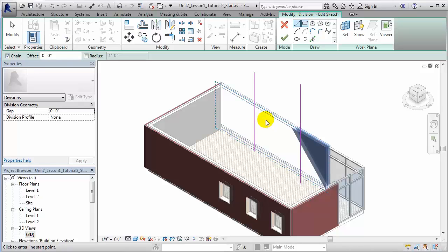I'm going to go ahead and place these vertical lines more or less here to account for how these wall segments will be installed. And besides the installation sequences, let's think about the penetrations. We can go ahead and draw shapes for anything that we might have going through this wall. It could be a conduit chase, or where we have a large MEP system coming through. Maybe we've got a group of pipes or a large pipe coming through. So I'll go ahead and add 2 perforations for situations like this.